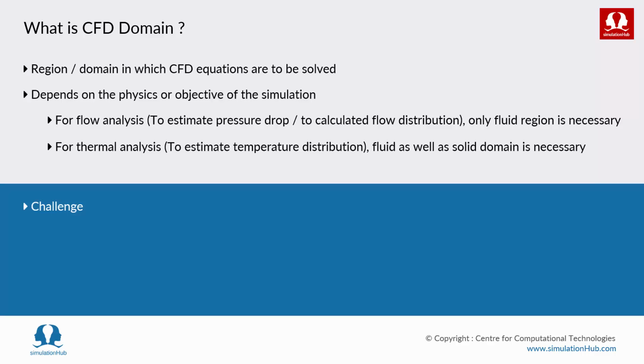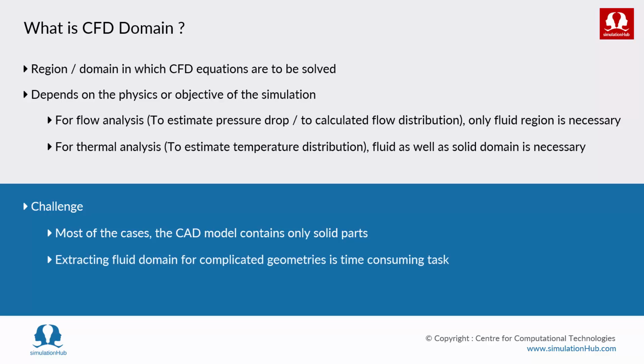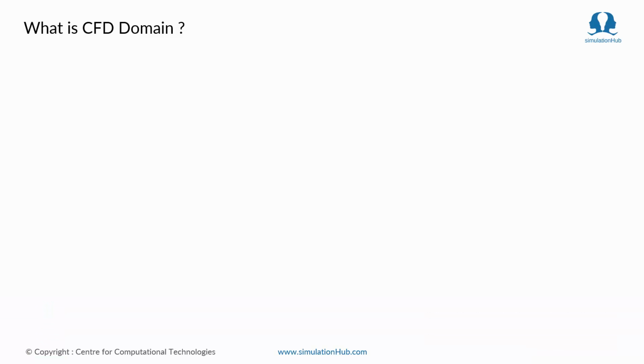The main challenge for defining a CFD domain is the complexity of the CAD model or the way the CAD model is created. Most of the CAD models available contain only the solid part. It does not have something called a fluid region. Now extracting a fluid region or a fluid domain is complicated for complex geometries and it is a very time consuming task. So let me elaborate more on what is a CFD domain.